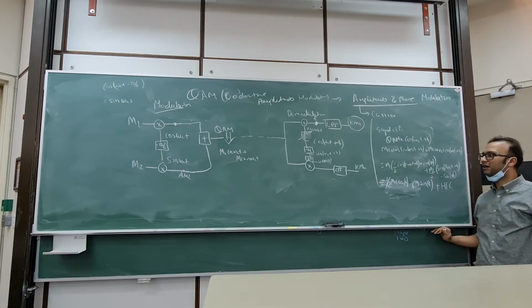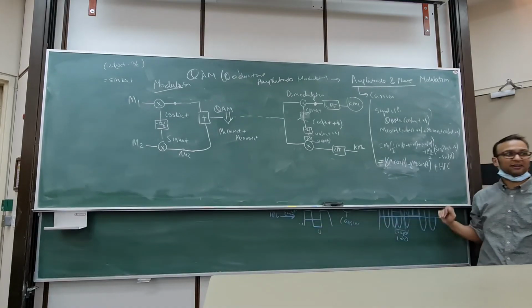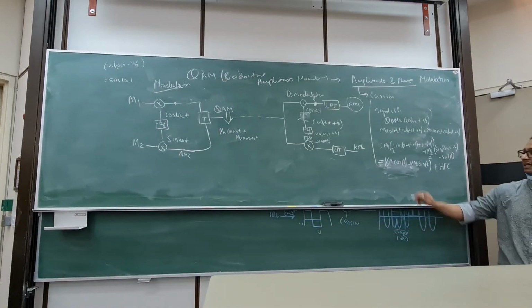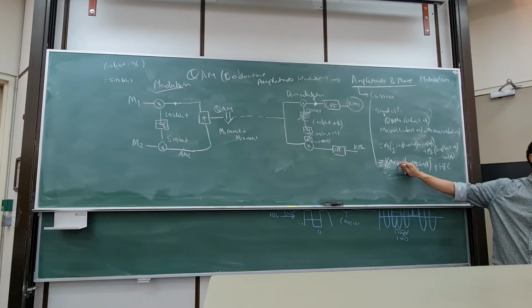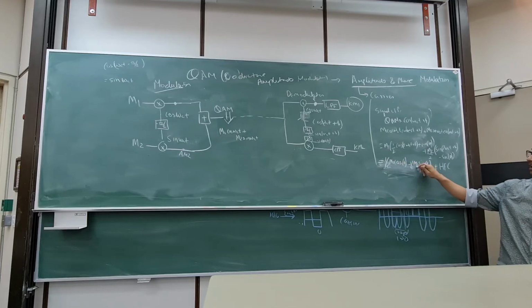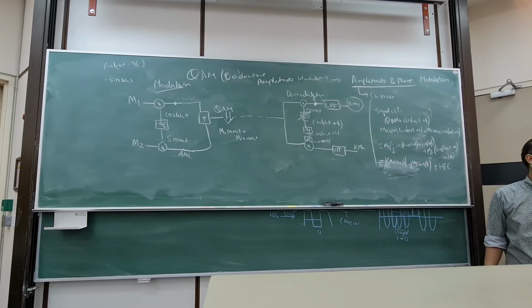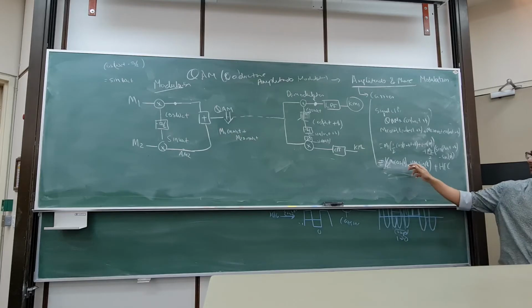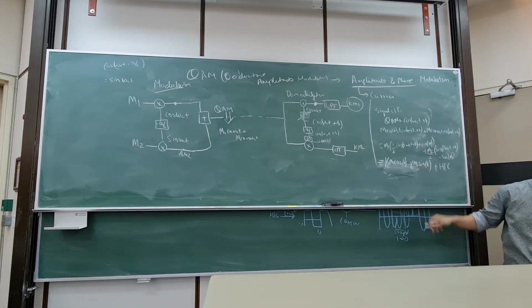Good. So now see, over here, do I have a scaled output? No. You see, half M1 cosine of phi minus half M2 sine of phi. Because this is a subtraction, you cannot just divide or amplify to recover M1.